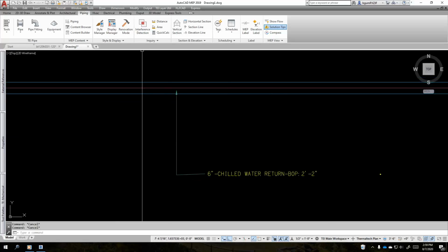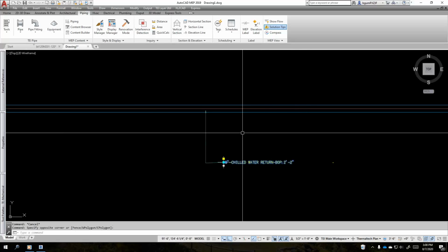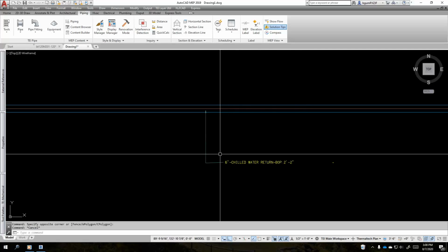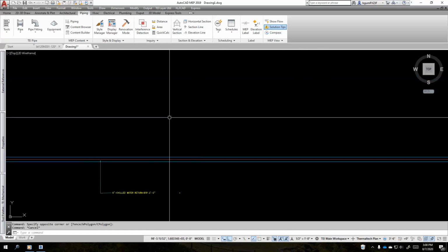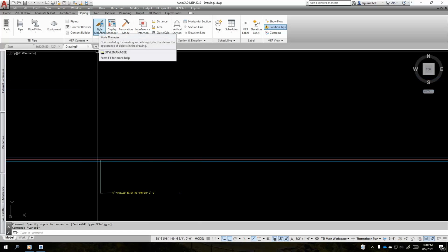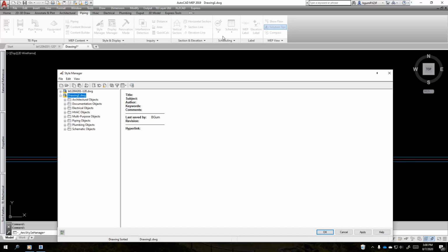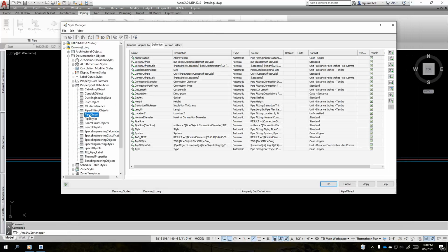And actually, we'll take this one step further. So you set this up. Ideally, you want to set this up in your TWT, your drawing template that your company will be using. That is the best practice. But for whatever reason, if you start doing this in the middle of a job and you need all the sheets within that job to inherit this, just open them all up, go into the one that contains your property set, and just drag it into all the other drawings.